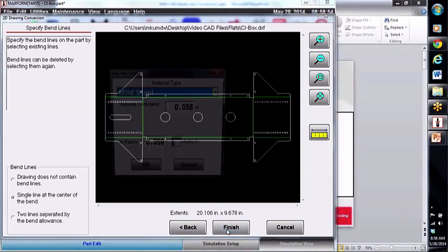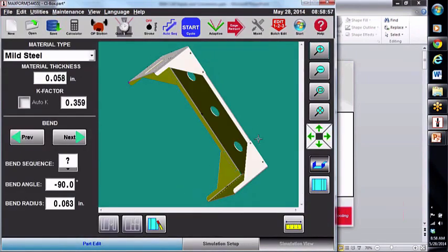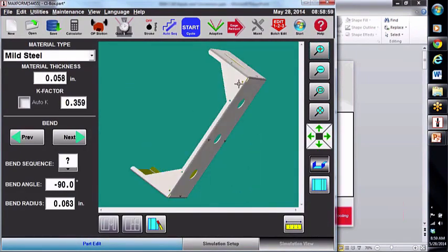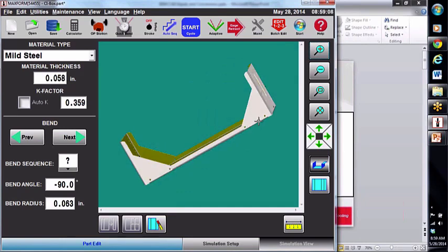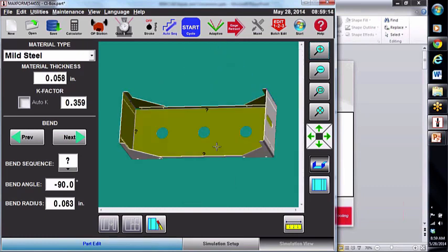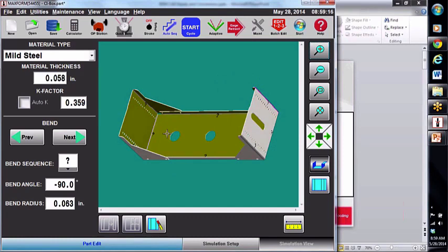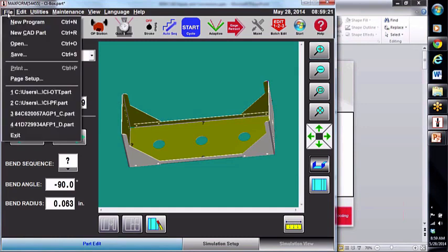Now let's fold it up. There. That's more what we're looking for here. So if this is a stainless part, this would lay on the laser or blank making machine like a turret punch press with the PVC coating up, and then this is what we're looking at inside the box. That would be the bottom side as it lays on the laser. Okay, let's do one more.